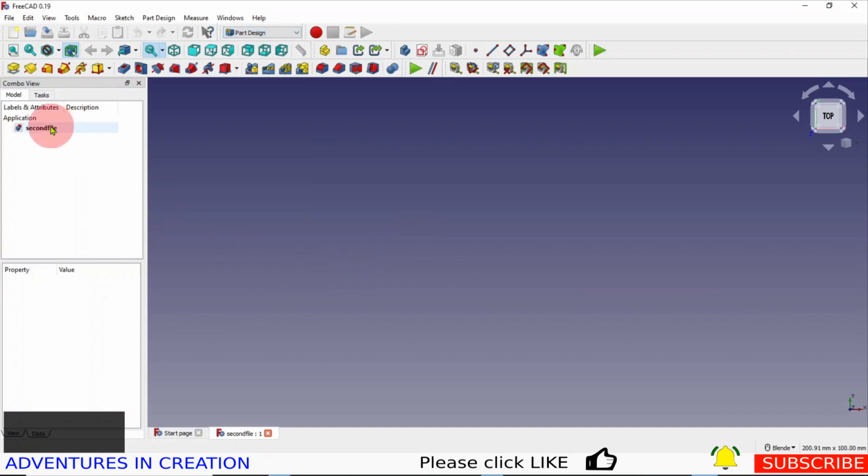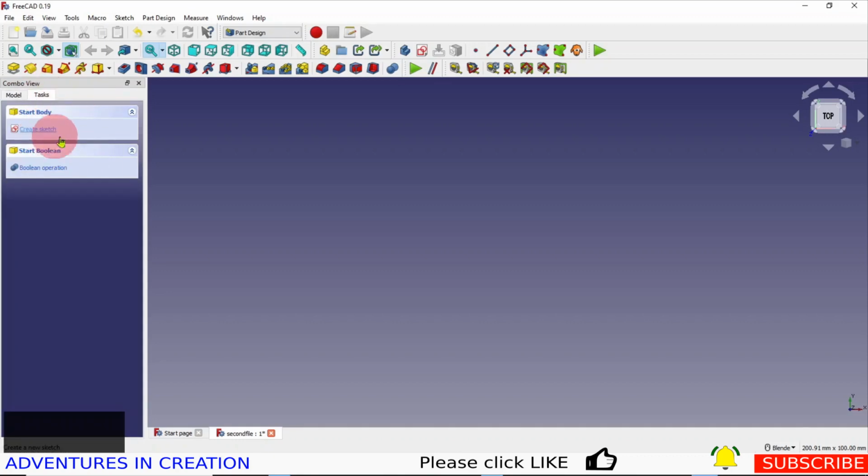So now I've created a file. I'm going to create a part in that file, so I'm going to use this create a new part and make it active. Then I'm going to create a body and make that active. And now we're ready to create a sketch. If we go to our tasks over here, so this is a tabbed interface, the next task on here is create a sketch. I can click this one, or I can go here and create a sketch.